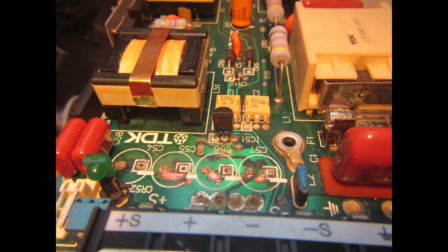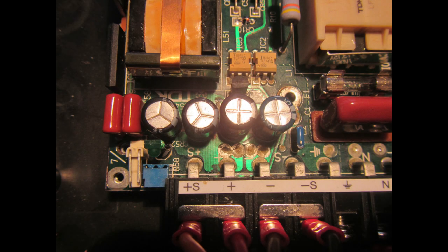It can happen that some of the solder mask gets removed. This is the enamel covering the copper traces, which is green in this case. It's always a good idea either to apply some light enamel to cover the exposed copper or apply some tin over the copper to avoid further corrosion and oxidization of the copper. Finally, I could replace the capacitors and assemble again the programmer.